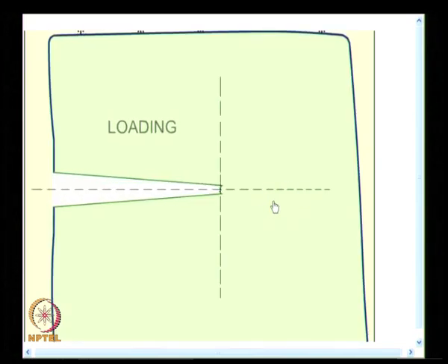As we understand the material more and more, you also find development of newer models, and this model really gives you an appreciation that in every cycle of fatigue there is incremental advancement of the crack, and there is also an impression created in the microstructure. So, this model you can accept it. Do not think that the crack initially propagates at 45 degrees in a ductile material. In fact, towards the end of the course we would look at several theories which would give you at what angle the crack will propagate for a given loading condition. That is a macroscopic calculation. At a microscopic level, what happens is what we are discussing.